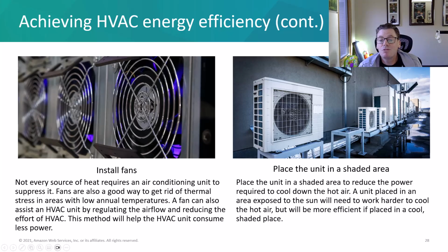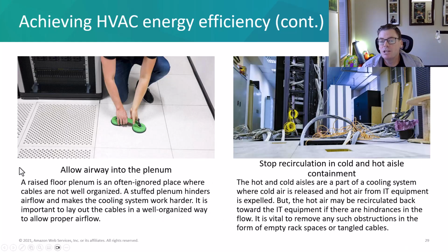We can put our outdoor units in shaded locations so that it can reduce the amount of power that it takes, right? If it's right out in the sun, we all know this. You put something out in the sun, it's going to get a lot hotter than if it's sitting in the shade. So if we can place our equipment in a shaded location, it should use less energy to cool things down.